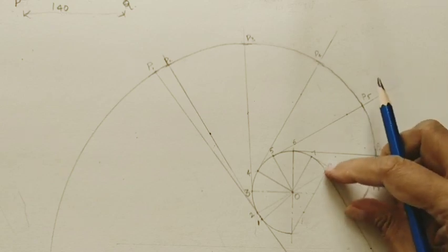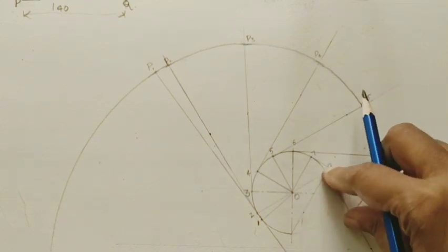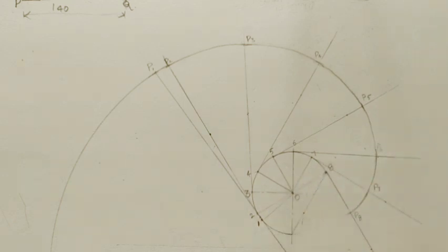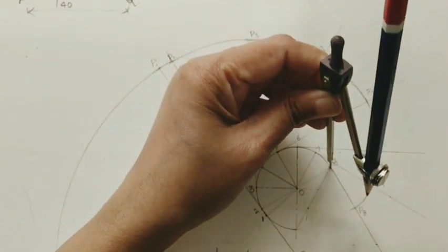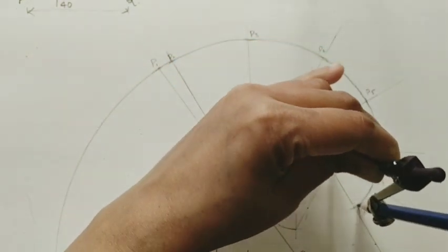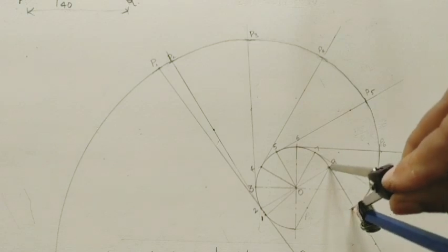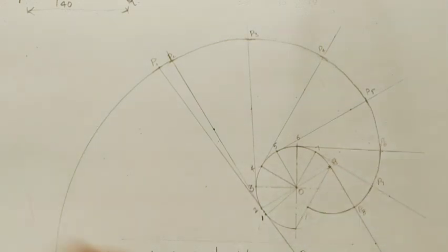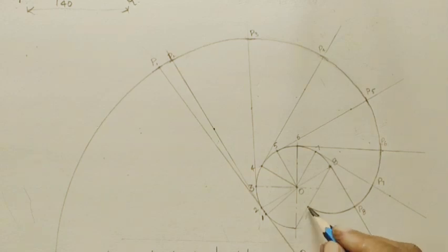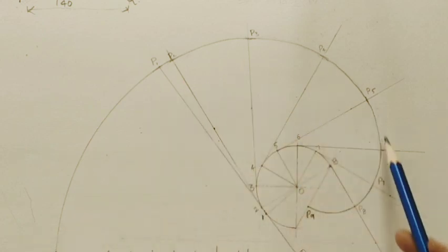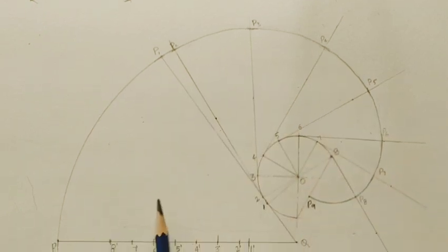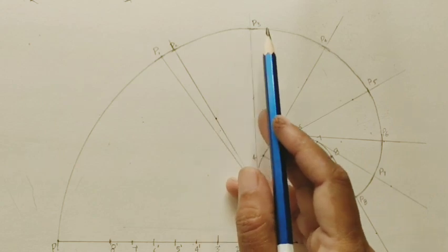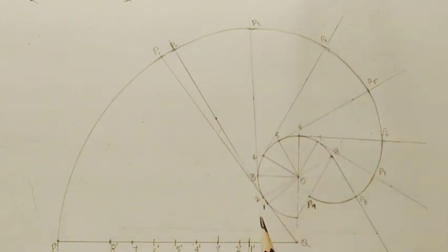Now whatever radius is coming, by using compass, take this radius up to this circular one. We will get the P9 point after P8 by using compass. 8 is center, P8 is the radius. Okay, last point. Join this point to the pole on one side like this. Now the intersection point is P9. We have joined all the points from P to P9. This is the path of the P end point when the rope is wound around the pole.